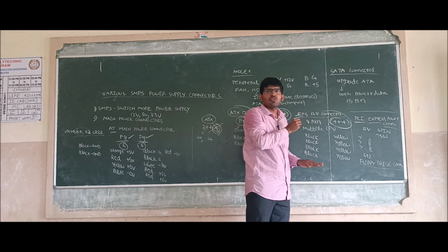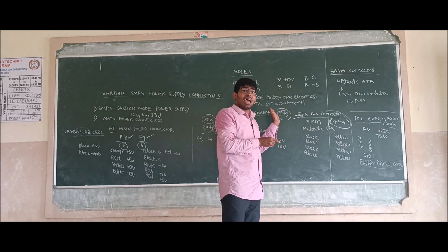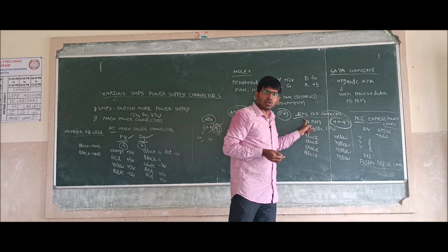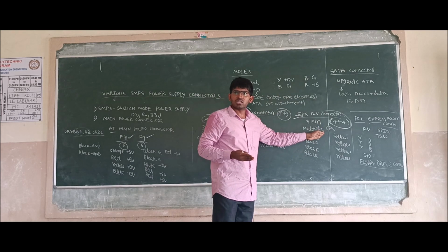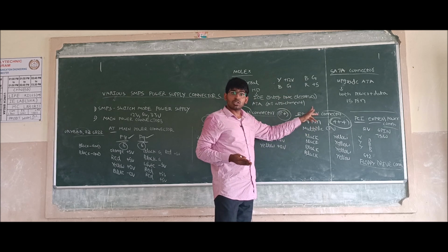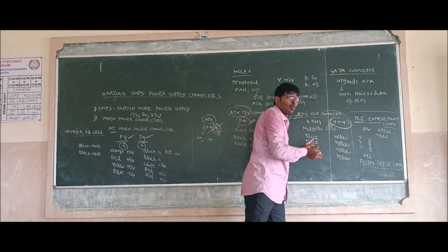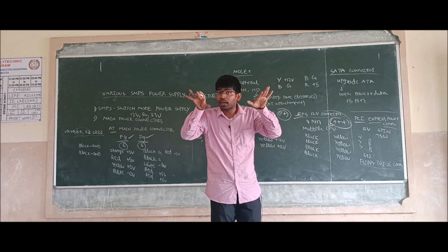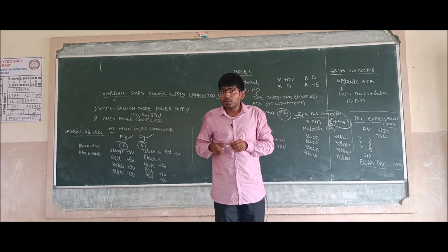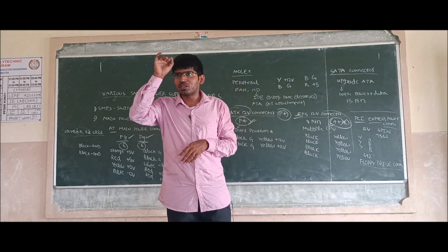But why are you writing 4 plus 4? Because, as we discussed already, it should be compatible with the earlier P4 connectors also. So whenever we are using this EPS 12 volt, which is the advanced version of the P4, we can replace the P4 with the EPS 12 volt. If I am using an older board whose processor has the capability to take 4 pins only, I can discard 4 pins. Yellow, black. But still those 4 pins are there.